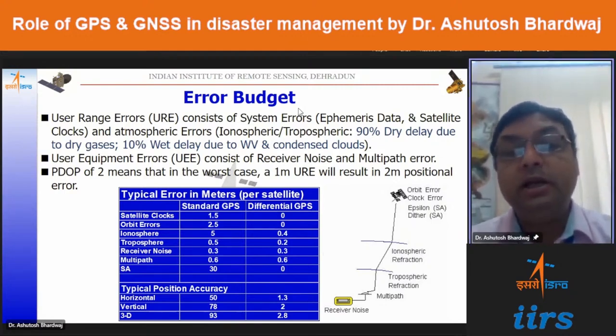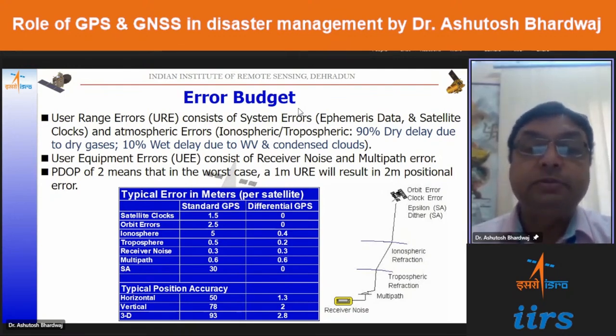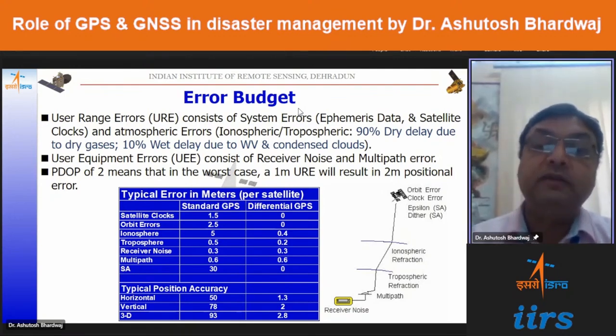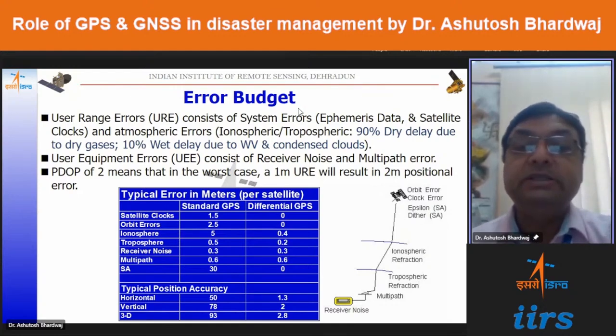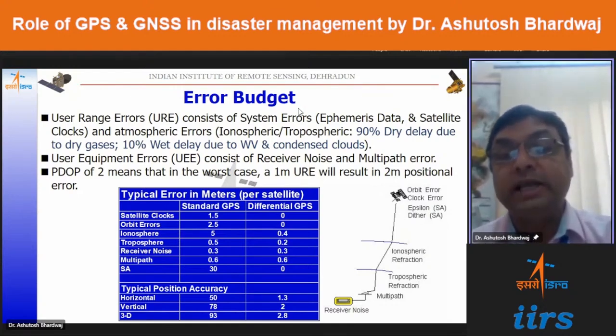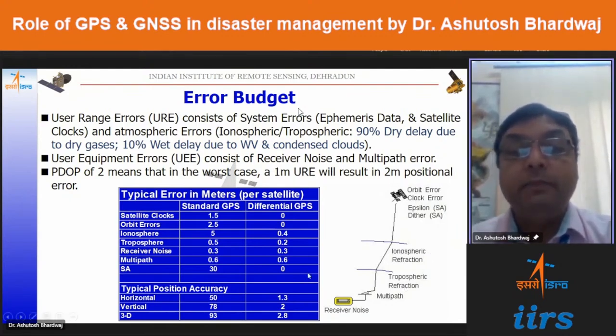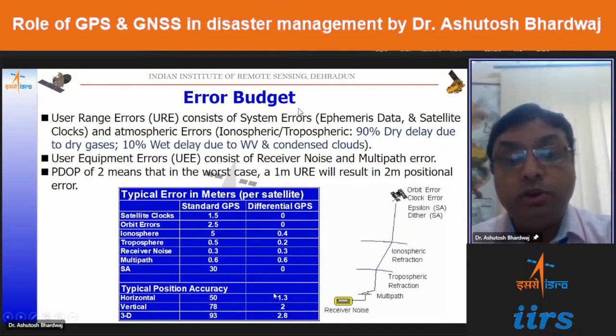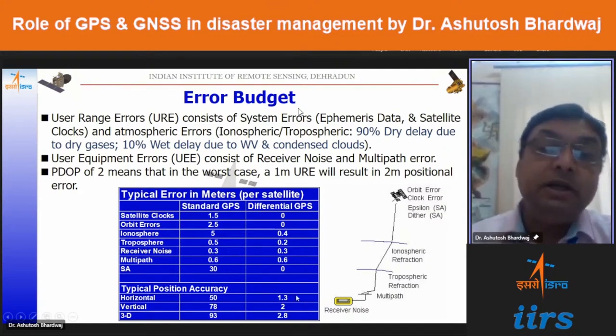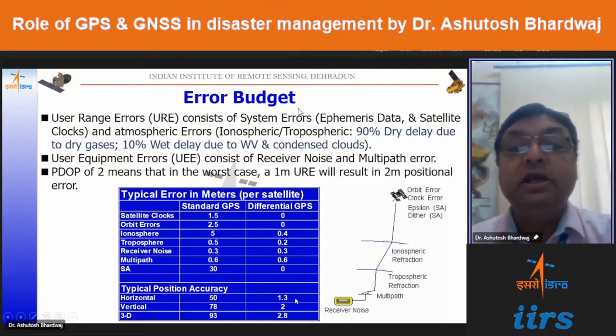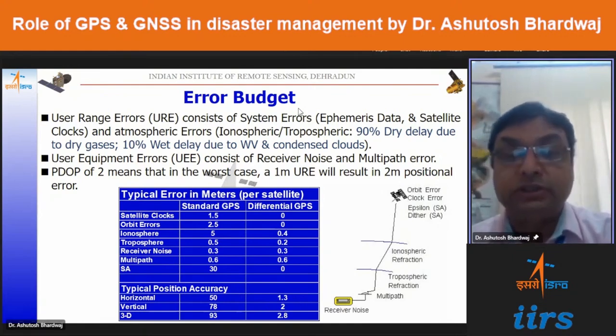Now these GPS systems, if we use them in the relative GPS mode or the differential GPS mode, where we have one GPS to compute errors having known location, then the DGPS system can be used to provide meter level of accuracies through the code solutions and millimeter to centimeter level of accuracies using the phase solutions.